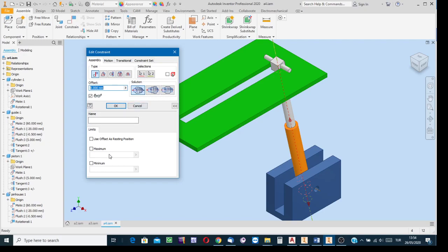And there is no limit, because I don't know at the limiting position how many millimeters the length of the piston part will be outside. I don't want to calculate this, so I didn't put any limitations. If there were no tangency type constraint between this cylindrical extension and the surface of the green one, the piston might just be moved to infinity, because there are no limiting positions.